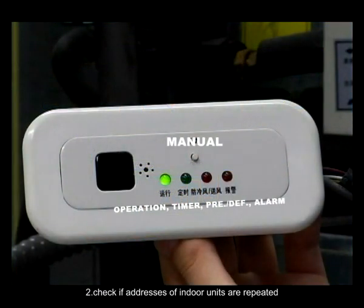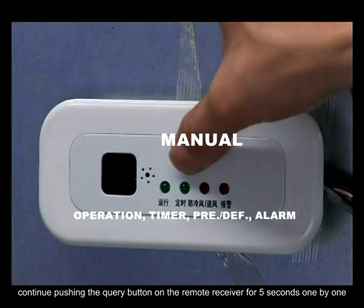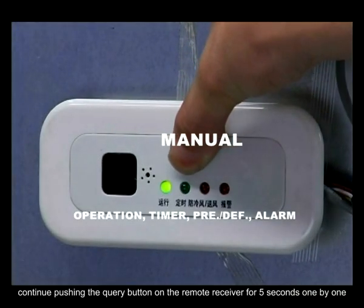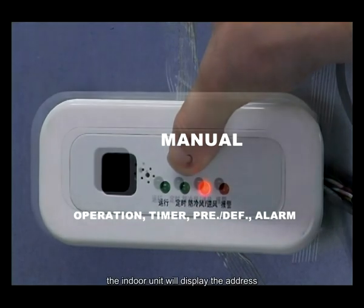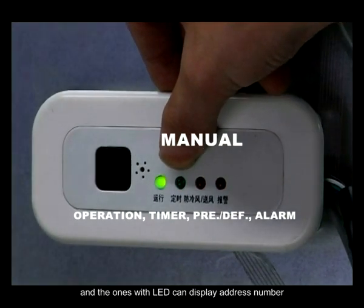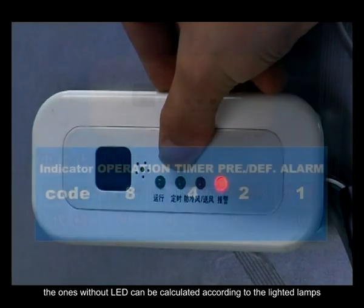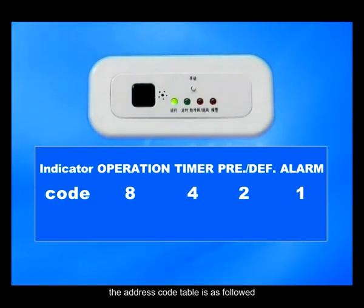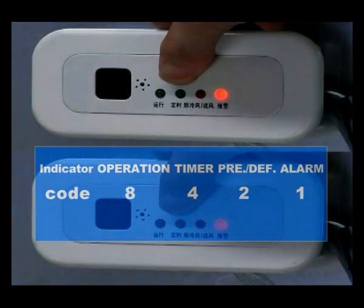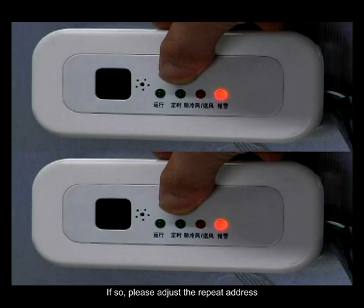2. Check if addresses of indoor units are repeated. Continue pushing the query button on the remote receiver for 5 seconds, one by one. The indoor unit will display the address, and the ones with LED can display the address number. The ones without LED can be calculated according to the lighted lamps. The address code table is as follows. Check if the addresses of the indoor units in the same system are repeated. If so, please adjust the repeated address.